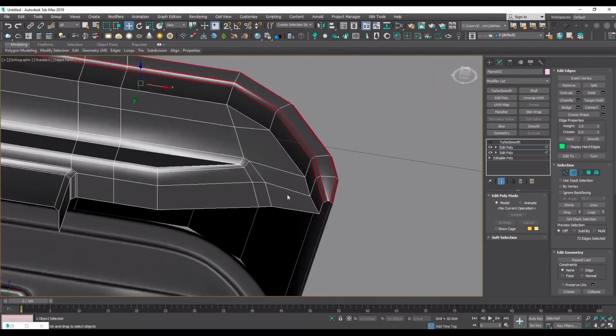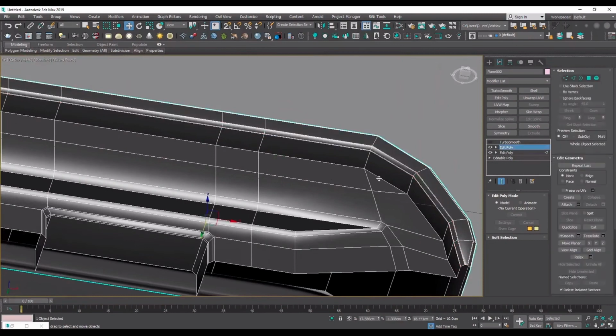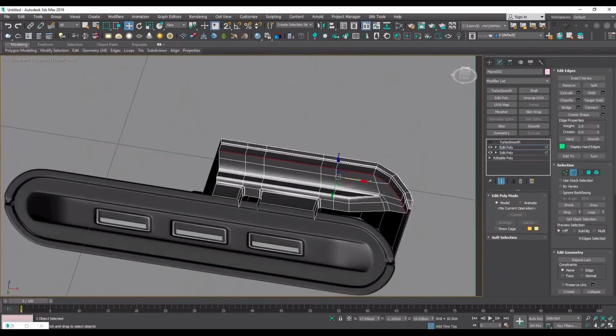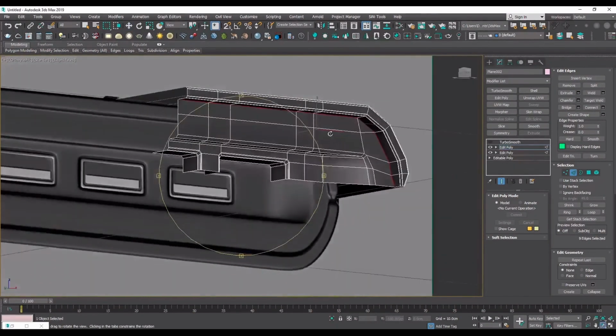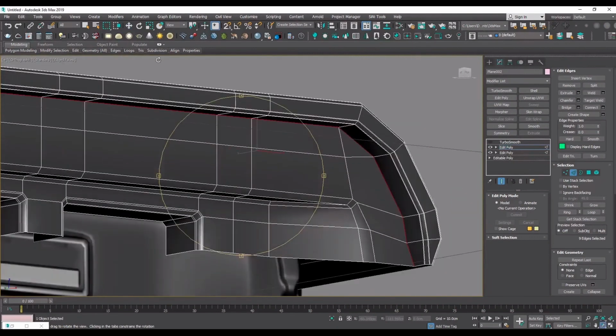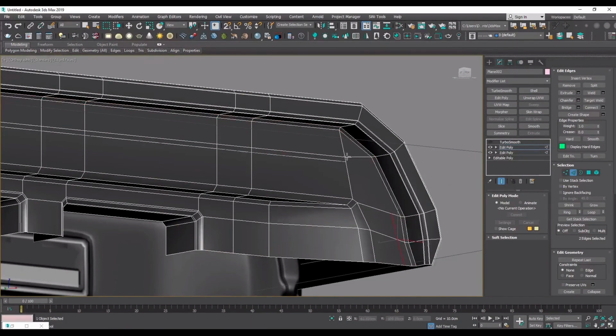And here as you see, I want to basically repeat the same process and select the edge loop on the surface and select the chamfer modifier to apply a little chamfer right here, and then I will want to create another edge loop across our flat surface.